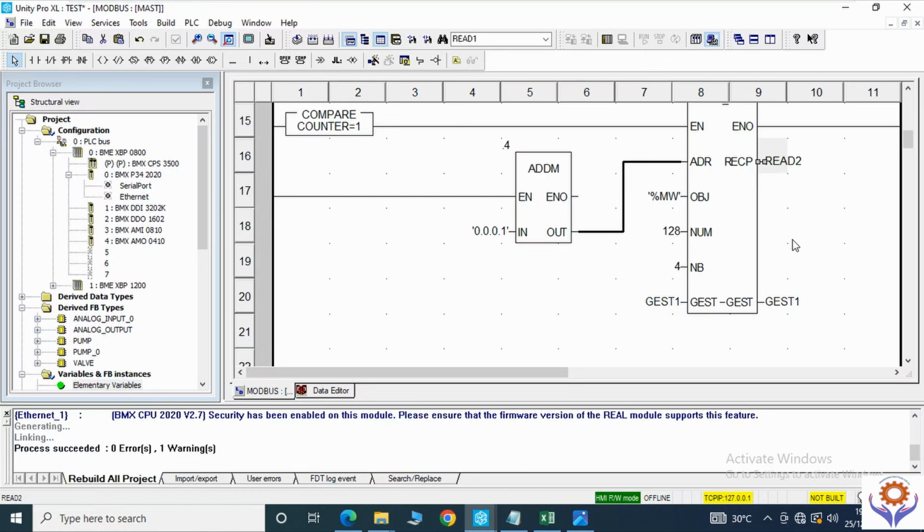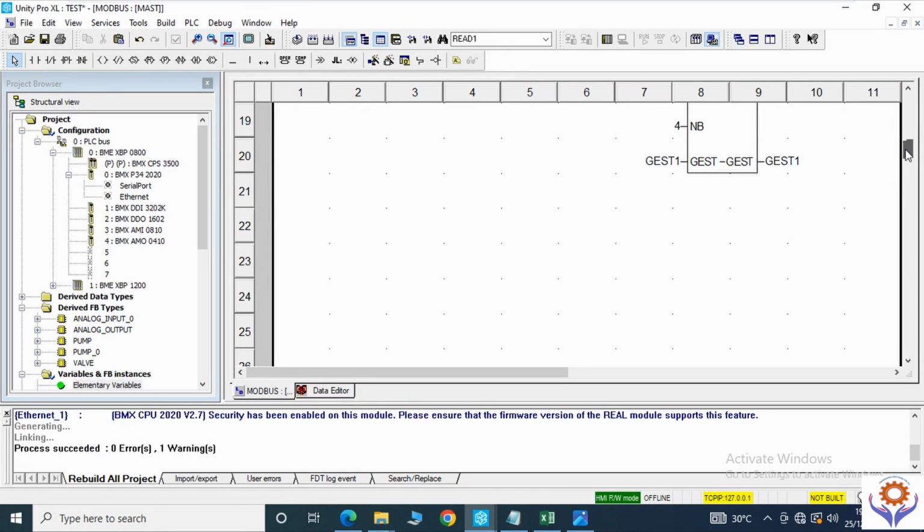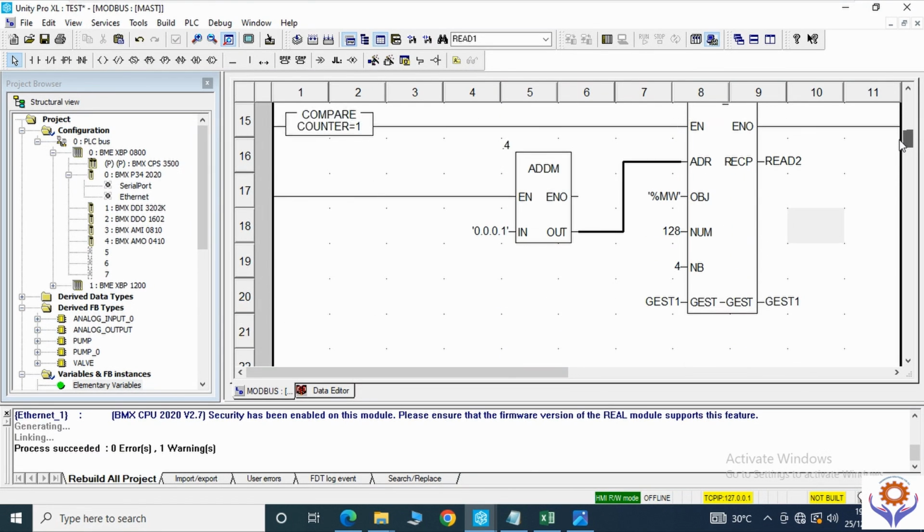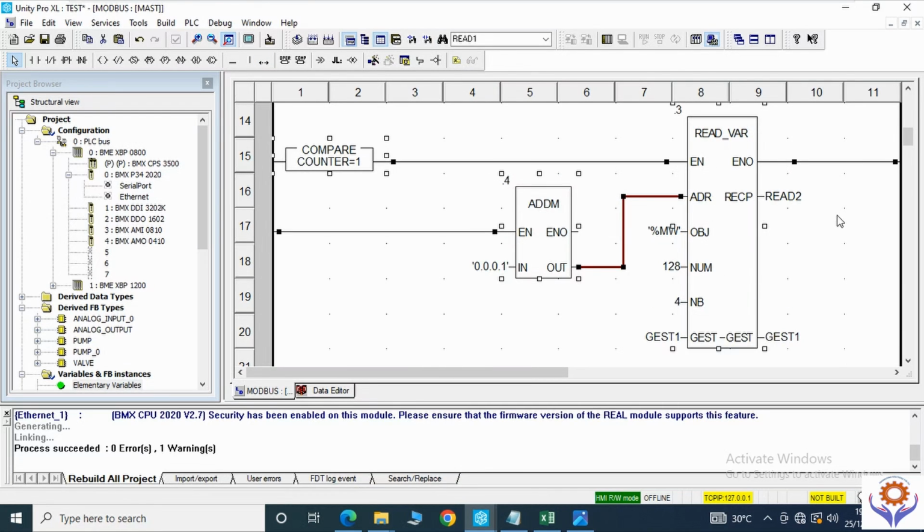Okay, these functions, see, and the other point I told you before: this is 0.0.0 and the serial number, and this one is your slave ID. Now your slave ID is 2. So you need to add this on the second one. For example, see, now you counted for the first one, and now I will move to the second power meter.